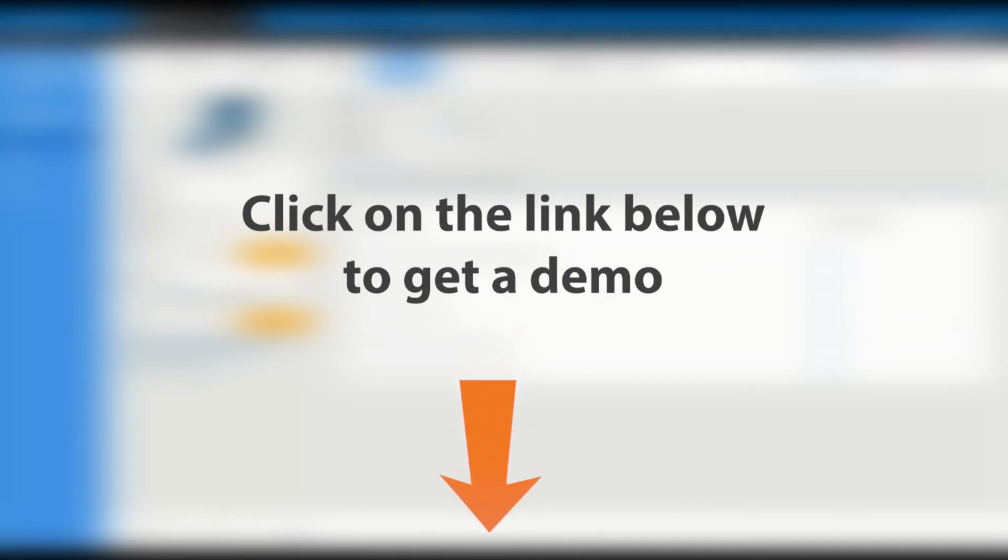Okay, so the monitoring task here, if you're familiar with lightweight M2M, relates to the observe and notify events in the lightweight M2M protocol. So we're actually creating an observe event for that edge device. We've selected a bunch of devices, and we've said we're interested in their battery level, maybe the memory, pressure, temperature, and maybe RSSI. So that's of interest to us.